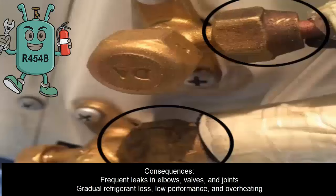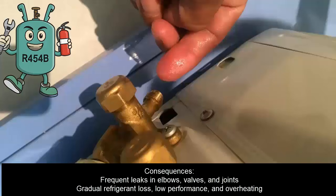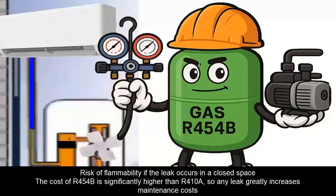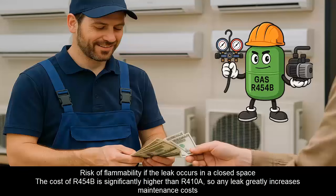Consequences: frequent leaks in elbows, valves, and joints, gradual refrigerant loss, low performance, and overheating. Risk of flammability if the leak occurs in a closed space. The cost of R454B is significantly higher than R410A, so any leak greatly increases maintenance costs.